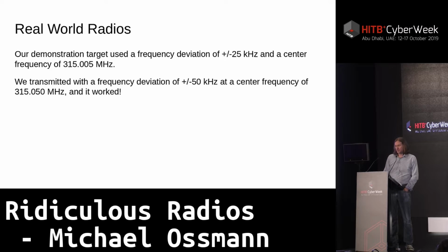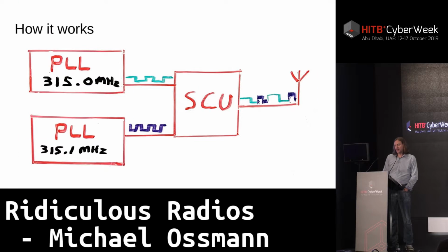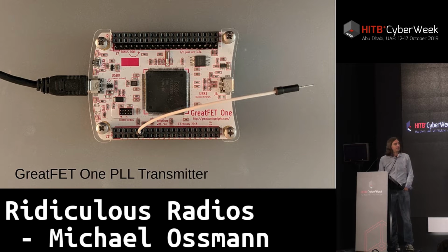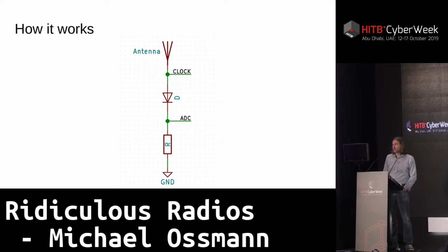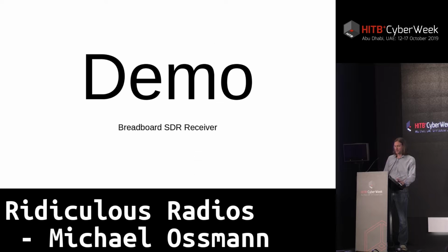I want to jump back through some slides here. I want to point out that this circuit has a certain similarity to this circuit. You'll notice that the clock is connected directly to the antenna in both cases. And so, in this one where I said it was a receiver, well, guess what? It was actually transmitting too. This thing transmits as much as it receives, which is pretty ugly from the standpoint of radio design, but it works.